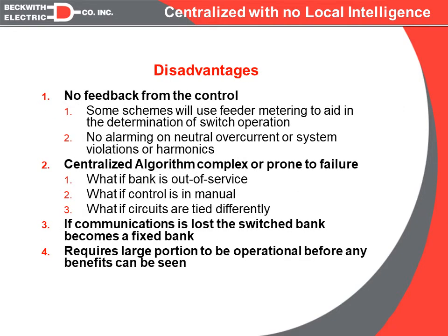The disadvantage with this approach, first of all, is that we basically have no monitoring feedback. Since it's one-way paging, we send a command out to the control, but we really don't know whether it operated or not in the way we asked it to. Now in some systems, they may be complex enough at the SCADA centralized algorithm that it will look at the feeder VARs, send out a command, and then anticipate the feeder VARs to change by that amount, and if it doesn't, it can generate a pseudo alarm to tell you that the bank is out of service.